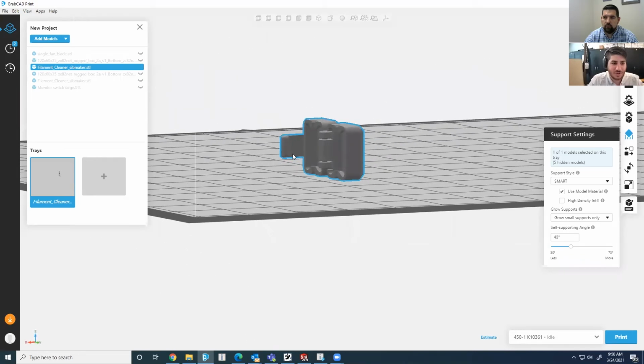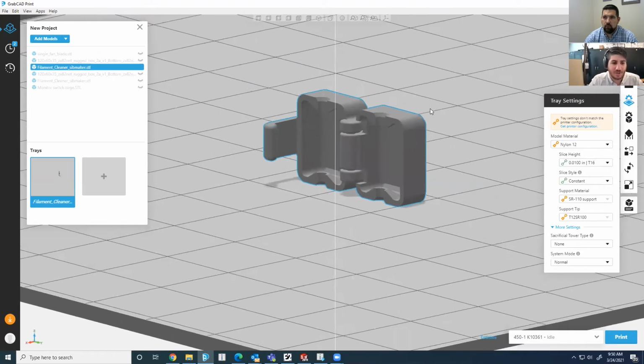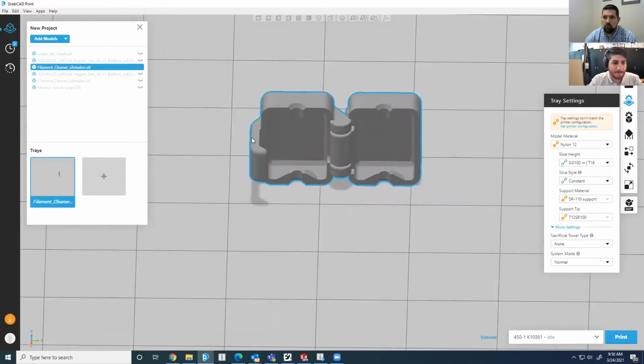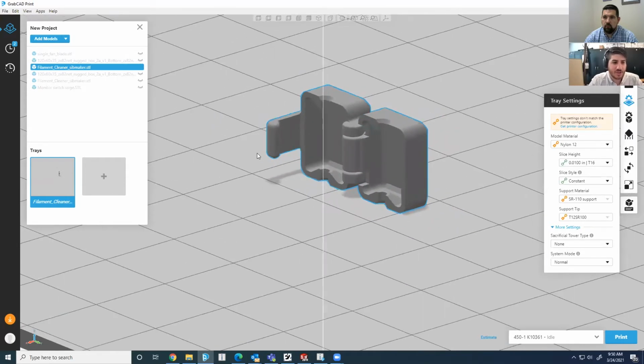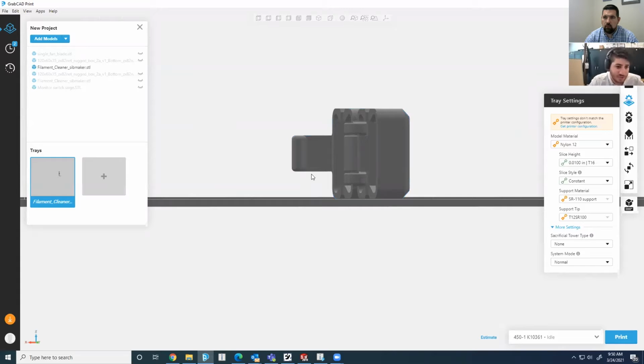as support. So if I was building in nylon 12, which is a very heat susceptible material, and it likes to curl in the machine. So this little arm here would be a concern to me, meaning that if I was building support material up to here, there's something called the coefficient of thermal expansion, which every material will deal with, and it is how much a material expands or shrinks in its environment dependent on the temperature. So the sacrificial support material and the model material have different coefficients of thermal expansion. So as the support builds up to here, it contracts a lot more than the model material does. So it won't have anything for this base to build on, and it'll cause this to curve up this way.